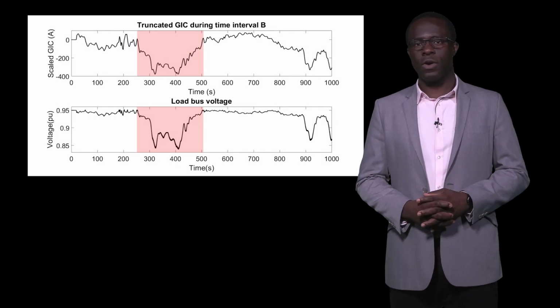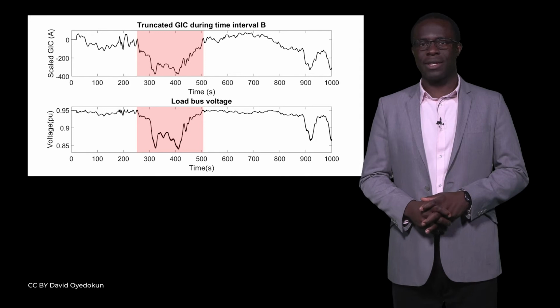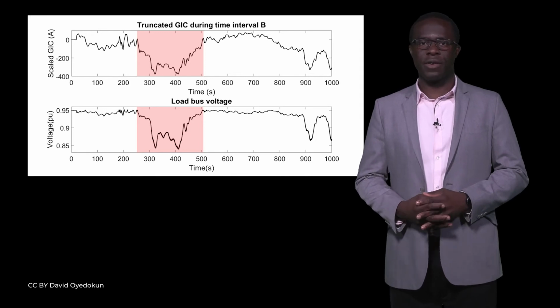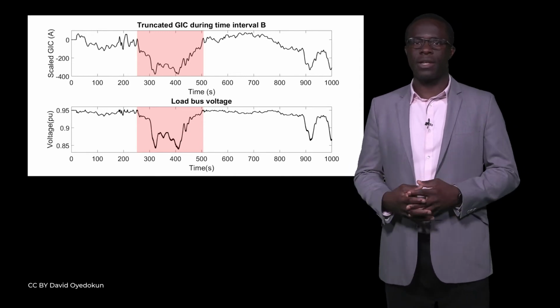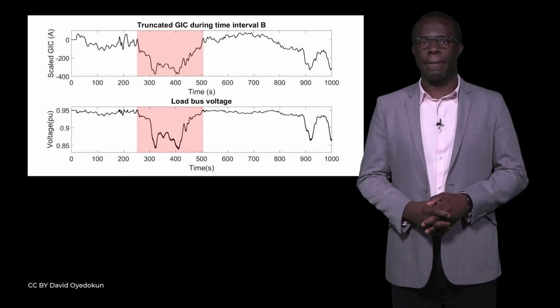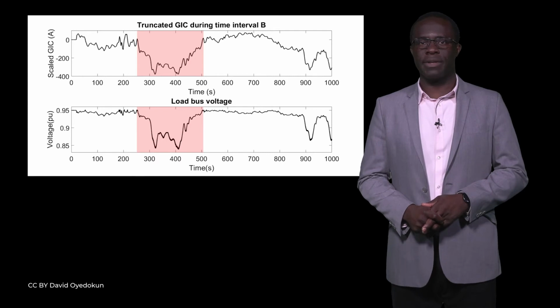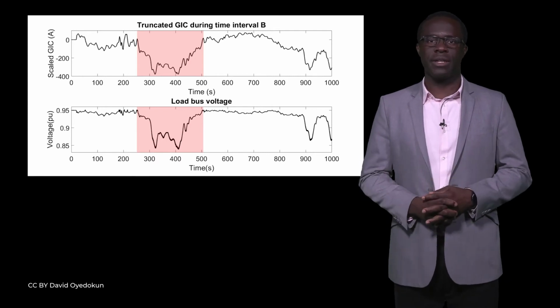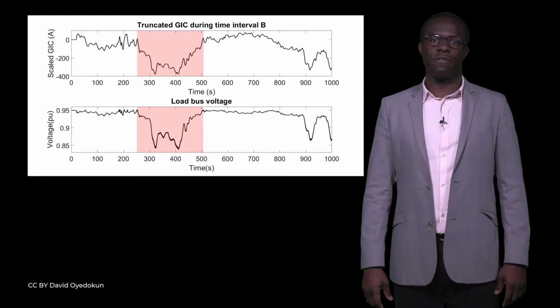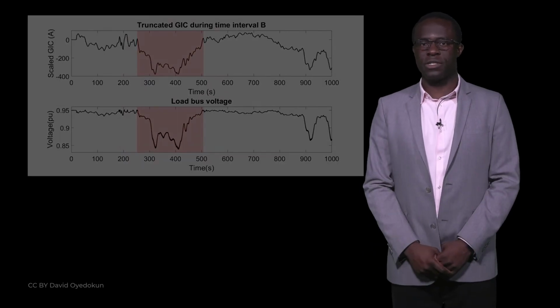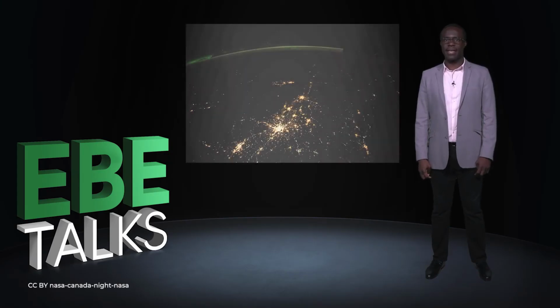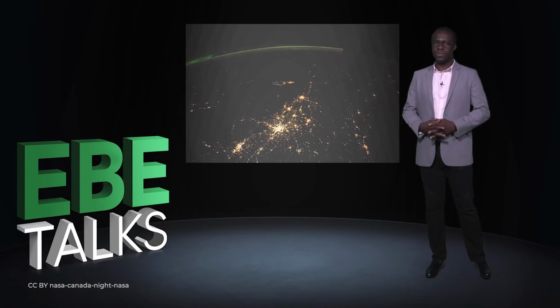These harmonics flow along transmission lines, causing an increase in the RMS current, power losses, and a decrease in voltage and power quality. These may also lead to voltage instability as generation cannot meet the increasing power demand to keep voltage levels within satisfactory limits. A classic example is the 1989 Hydro-Quebec blackout. The power system rapidly collapsed within seconds, leading to both technical and economic implications.